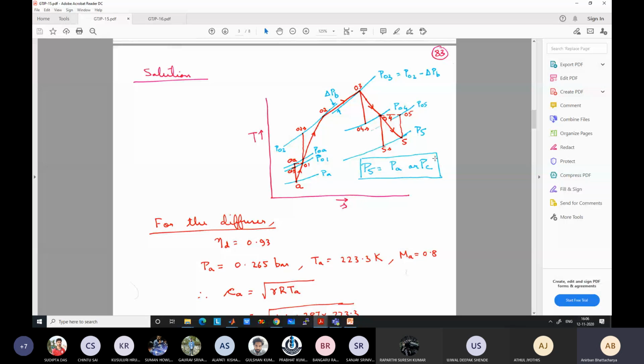This is only considering the engine. There are other benefits also at higher altitude, like the drag is less because of the thinner air, but the lift is also less. That is a drawback, but the drag is less. Okay, but those are external conditions. Internally to the engine, the fuel consumption is improved, meaning you need less fuel, because less compressor work input is required.